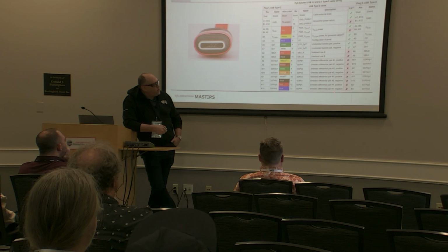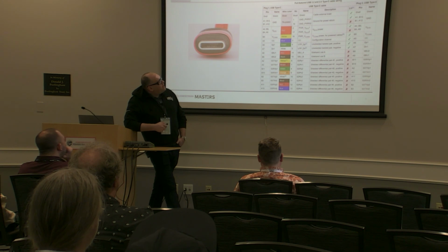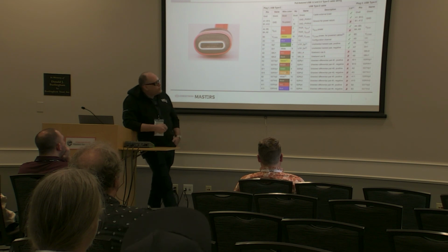And then we've added another set of differential pairs. So that's our high-speed bandwidth. When we actually do DisplayPort alt mode, that's where we're going to see that. Other things to talk about is we do have this VCONN pin, and we've got that second lane of power, right? And then there is this extra ground pin. That's for the shielding that's around all of these. They all connect to that drain pin for the differential pairs.